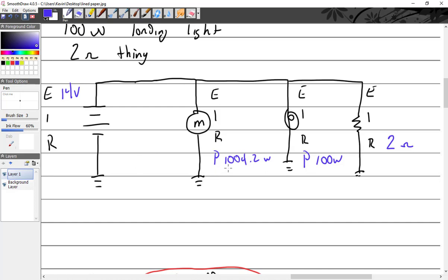That wasn't so bad. Okay, so I'm going to say it's 14 volts, 14 volts, 14 volts. Can I solve for my resistance? No. What can I solve now? I'm kind of stuck. Current here, current here, and current here. So how am I going to get that current there? Well, remember it's pie. I like pie. P equals I times E. But I'm trying to find I, and I have P. So we just move things around a little bit.